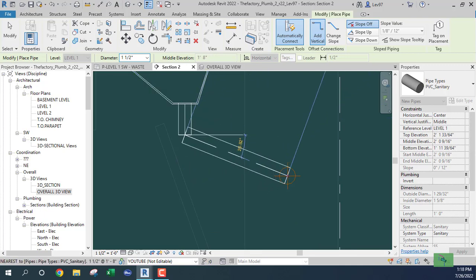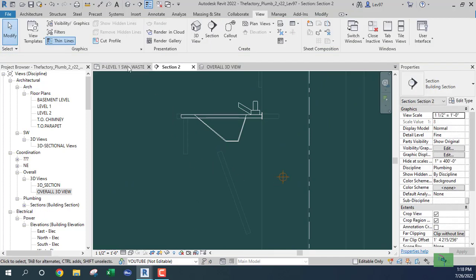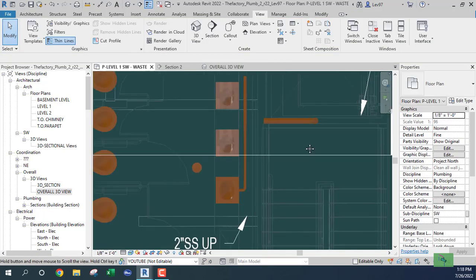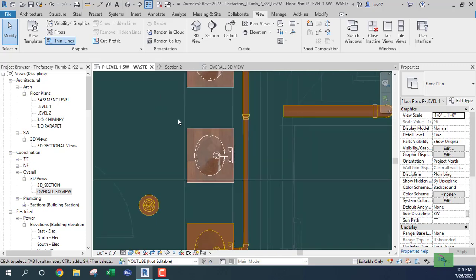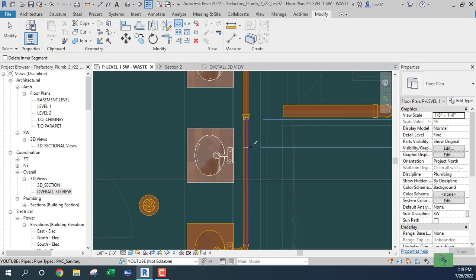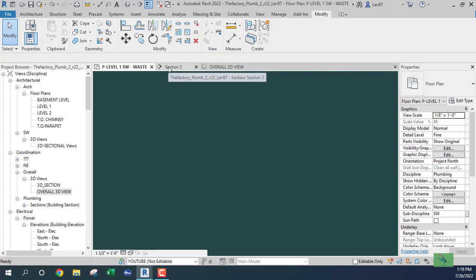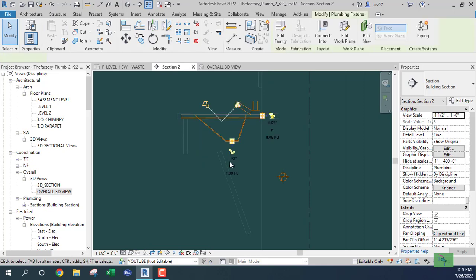What I'm looking for is my dynamic connection. I call it a dynamic connection. I didn't see it. So the trick to finding that connection is if you click on your pipe and put a little coupling in it, just put something in it to make it open-ended somewhere. So you have it open-ended, then you go back.